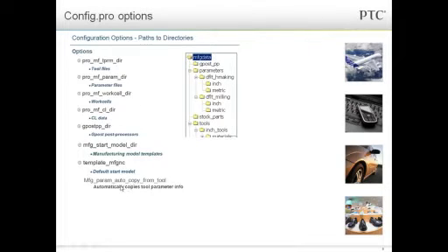The last one that you have right here, I added this one into this little slide that I have kind of late. For those of you that are using the software right now, one of the things that you notice and that you deal with on a given day-to-day, again, depending on how you have the software set up, is the filling out of your parameters, or essentially toolpath behavior. When you're filling out, I want it to be 1,000 RPMs and 50 inches a minute, and I want to go this depth, or I want to step this far and step over this far.